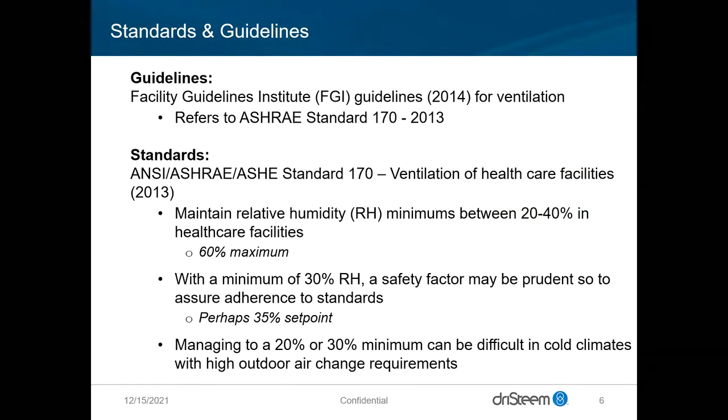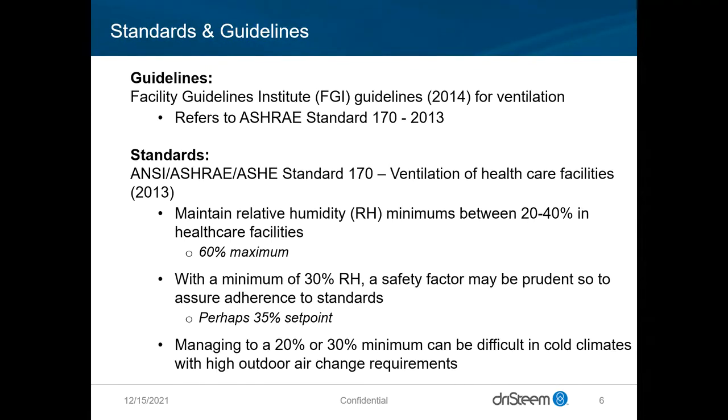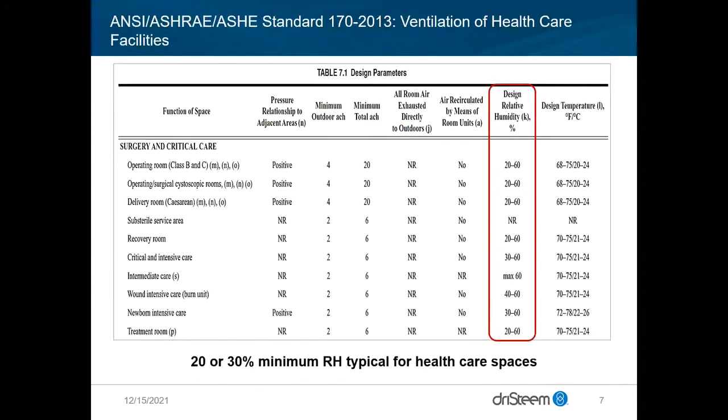There have been a number of guidelines and recommendations. The most notable in ASHRAE world is the healthcare facility standard 170. And you can see that there's a lot of different humidity levels depending on the application. So keep that in mind if you're designing for healthcare facilities, that you want to make sure that we keep